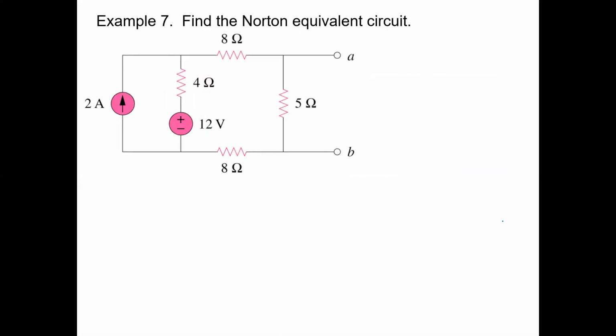So we're going to find a Norton equivalent circuit of an example here, and it's the same deal with dependent sources. This one only has independent sources, so it's pretty straightforward. But just to get into the habit, you can say that I Norton is the short circuit current. So we can actually put a wire there and see what that short circuit current is and use that in our model.